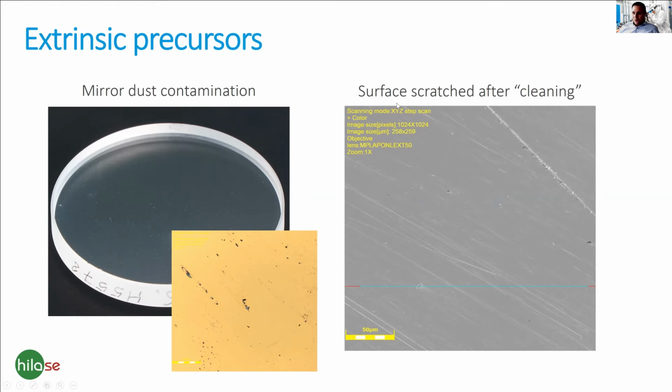Of course, when you do it in the improper way, all these dust particles on the surface, which may be even harder than the surface of the mirror itself, act as an abrasive on the surface, and you will induce such scratches or even such digs on the surface of the mirror, and of course this is not helping the element performance or its damage threshold.